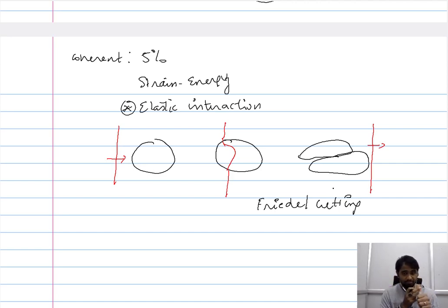So by the interaction between the coherent interface and the dislocation, they impede the movement of the dislocation, and when the overall particle interacts with the dislocation, a considerable amount of the driving force that dictates the propagation of the dislocation is consumed for the breaking up or fragmenting of this brittle particle. So in both these ways, the creep resistance is enhanced because both these ways reduce the rate of plastic deformation at a given time.